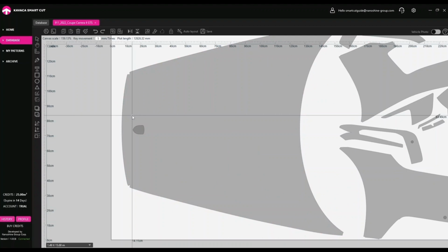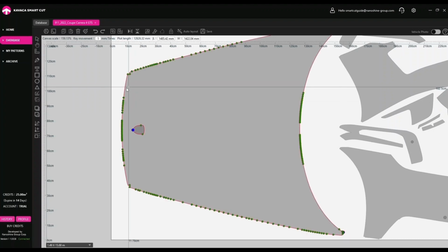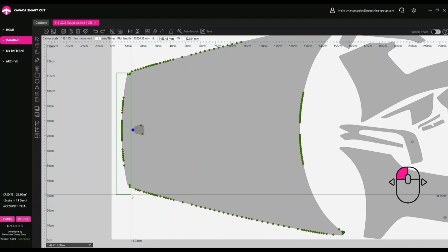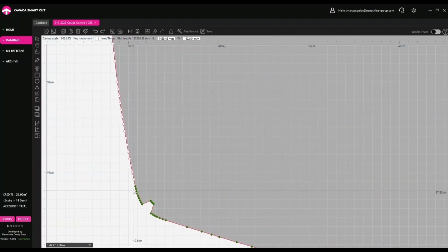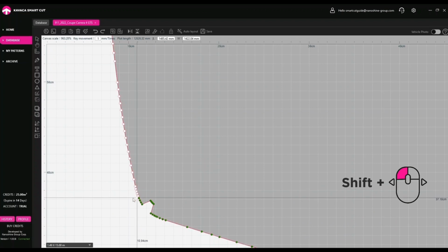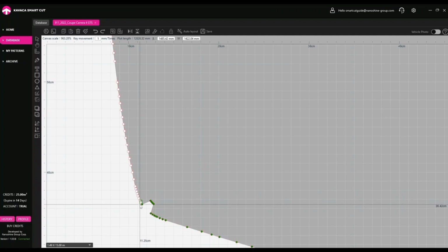In Edit mode, select one or more points, hold Shift and select additional points. If you have selected unnecessary points, then by holding down the Control key and selecting certain points, you can deselect them from the total number of selected points.